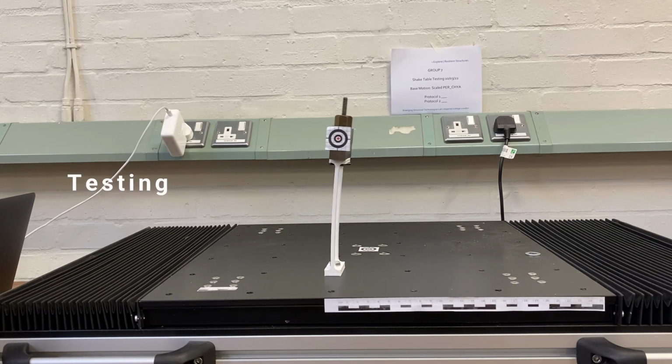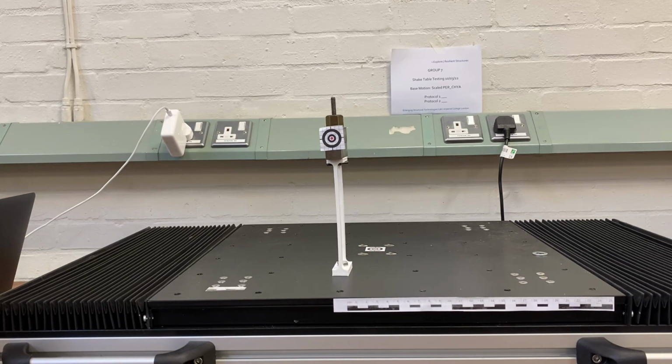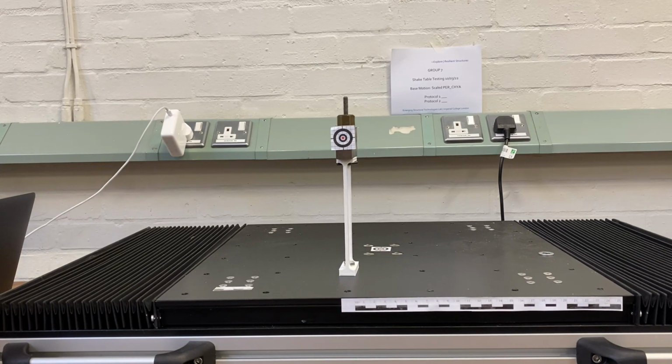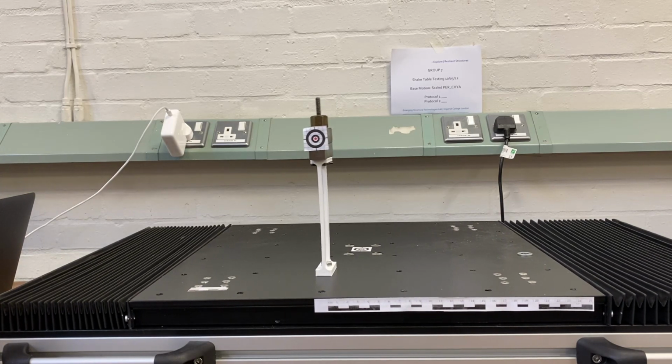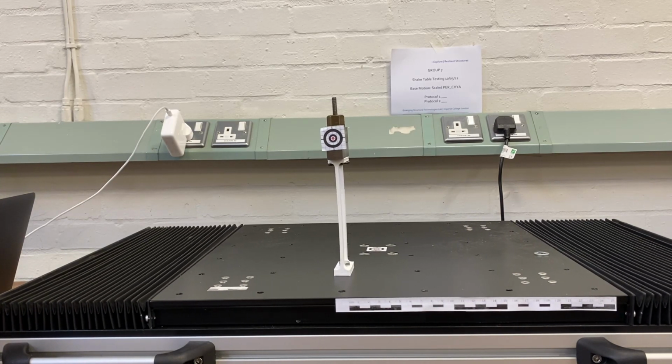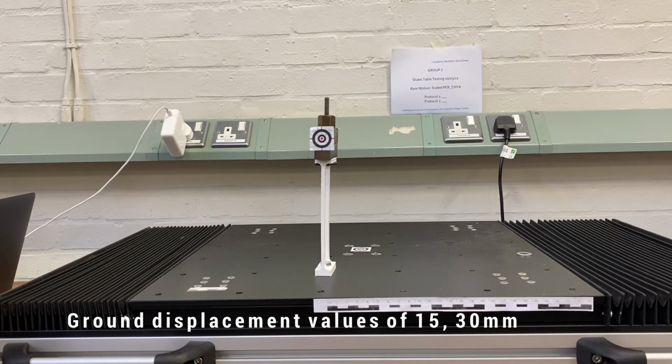In terms of testing, the structure is fastened with 2 metal weights on the top with a bolt and nut. It is then fixed to a servo mechanically actuated unidirectional shaking table, also using bolts and nuts. For the shaking test, the acceleration record of the northern Peru earthquake is used, scaled to a peak ground displacement value of 50 mm and 30